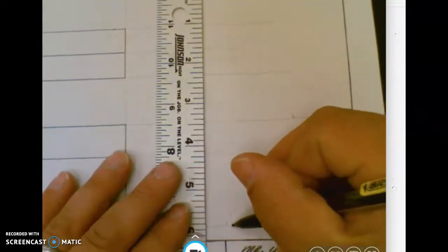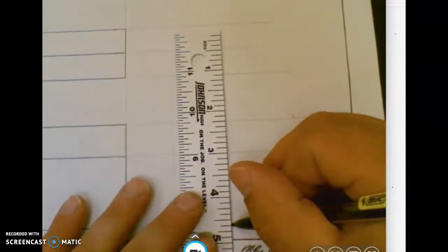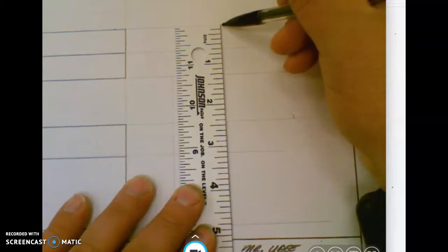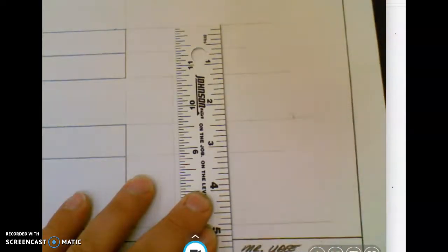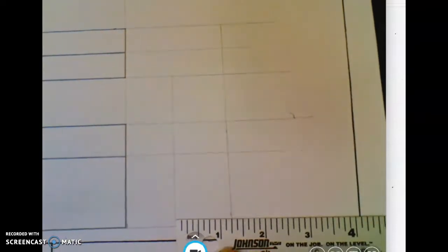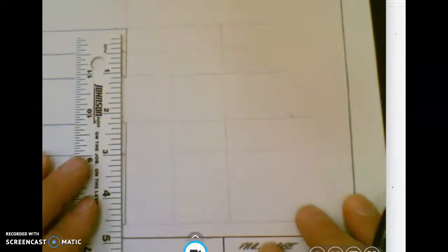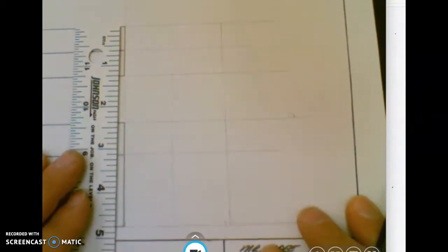And I'm now going to extend those two marks from the bottom edge of my side view here, you can see. And I'm going to run those up, and they're going to stop on the back side of my top view. And I'll show you why here. So we're going to start here, and we're going to come all the way down nice and light. So now I've located that 1 1/4. So that's 1 1/4 depth here, which also is going to be, as you saw in the previous video, 1 1/4 in my top view.